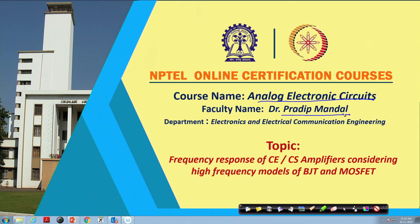Today's topic of discussion is frequency response of CE and CS amplifiers, common emitter and common source amplifiers, considering the high frequency model of BJT and MOSFET. In fact, we have already started discussing the frequency response of CE and CS amplifiers, but there we did not consider capacitances associated with the MOS transistor itself.